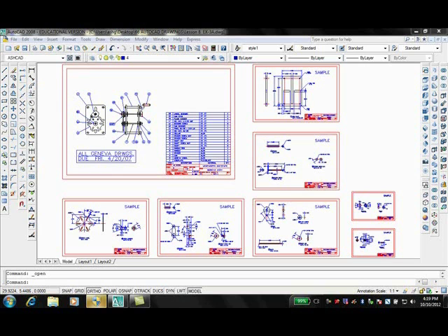The standard B-size format is 11 by 17, and if the format is inserted at full size, 1:1, the drawing would be too large to fit on the format. As a consequence, the B-size format has to be inserted at twice its size in order for the drawing to fit properly. On the other hand, if the drawing is not too large but looks good, there is no need to scale the format. The 5 drawings in the middle appear to fit properly at 1:1, so there is no need to scale the format for those drawings.